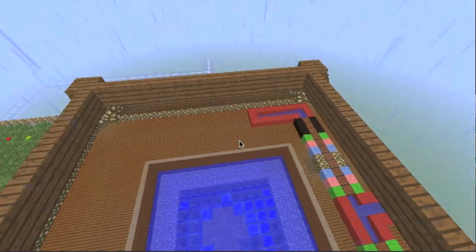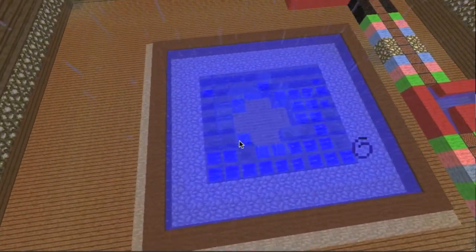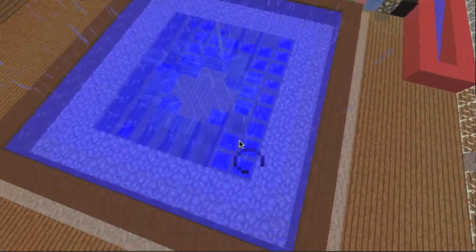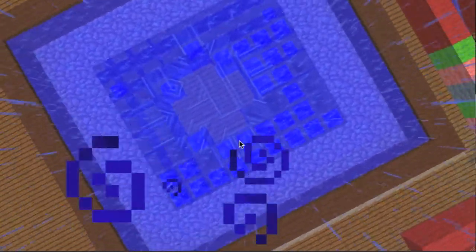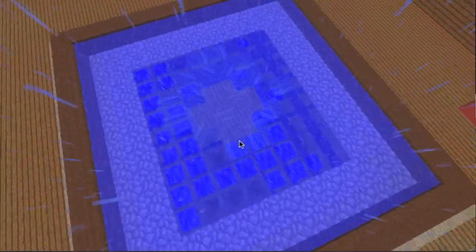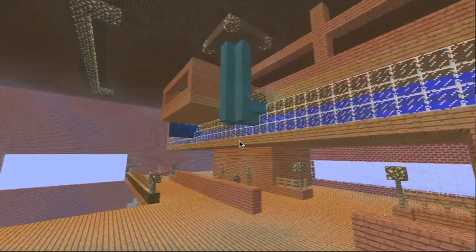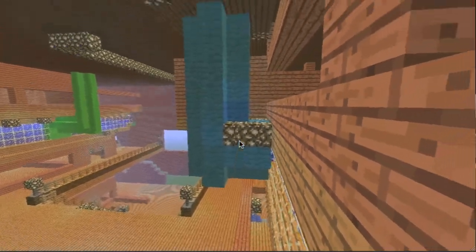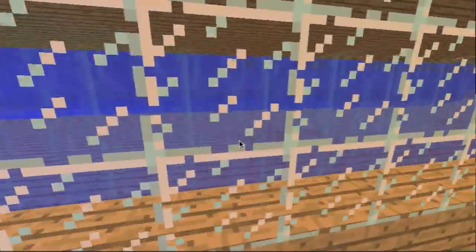Another structure or method in the school is water collection. Water collection is very important, especially in countries where it rains a lot. It consists of big containers on the roof collecting the rainwater, where gutters or pipes later transport it to a rainwater tank. The rainwater tank size depends on how much water you want to store in it.